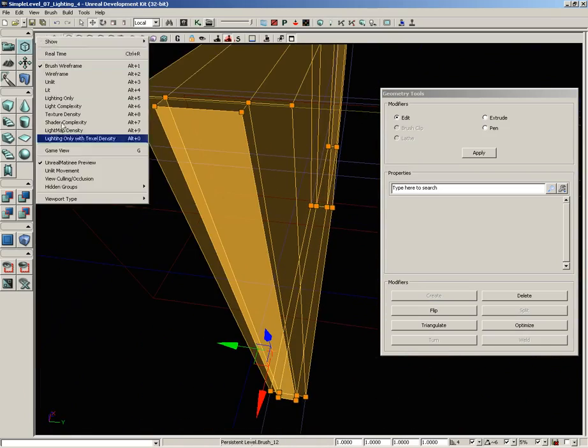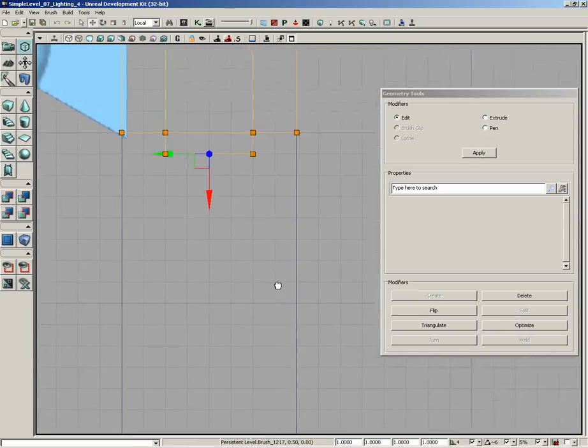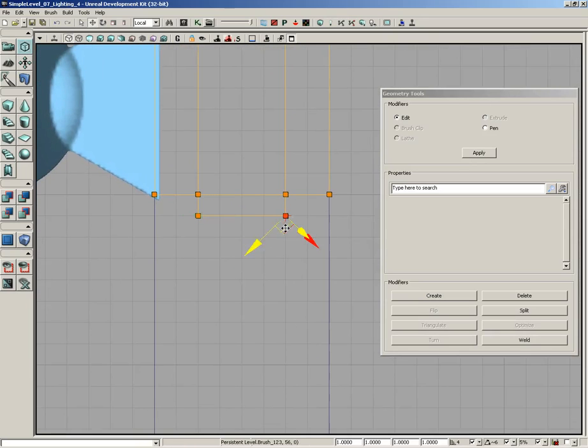But if we switch over to the top viewport, if we're feeling just that kind of cool, we could grab the vertices here. Let me make sure that I'm moving in world mode. So I'm going to jump up to the main toolbar and set my reference coordinate system to world, and we'll slide these vertices to the left, grab these vertices and slide them to the right. So now that pocket's got kind of a beveled look to it.